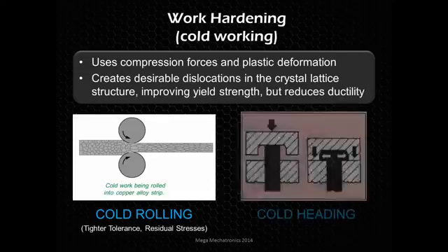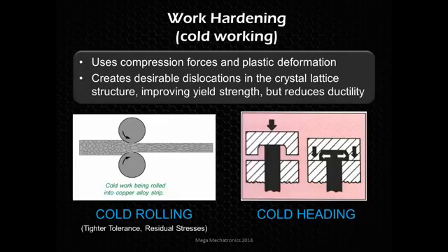Cold heading, this is a process of putting the head on a bolt. So you see that die comes down and plastically deforms it. And it does work harden that head and make it a little stronger.